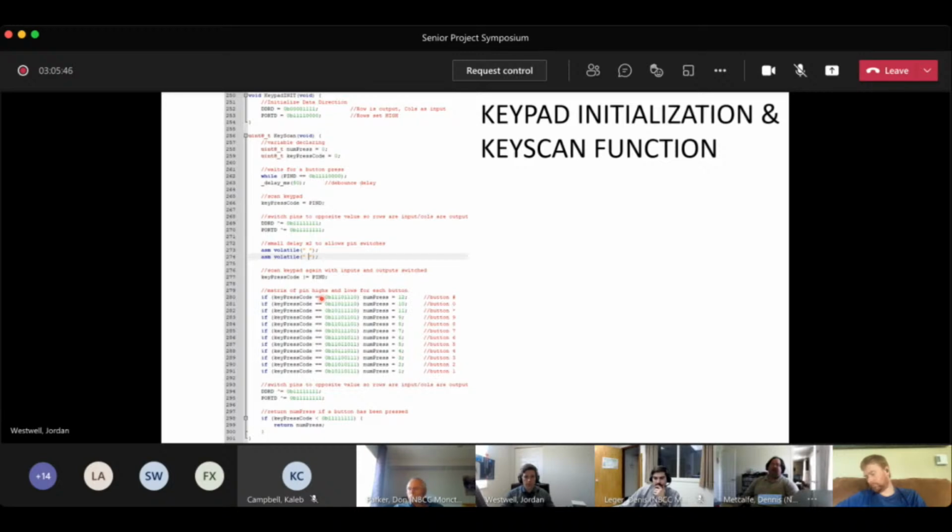Yeah. And also where you do the ASM volatile there for a delay, you might look into the ASM function no operation. I saw some that had no-op and some had nothing in it. No-op does the same thing. It just takes a time operation statement and doesn't do anything, right? So this is what it is equal to, anyways.